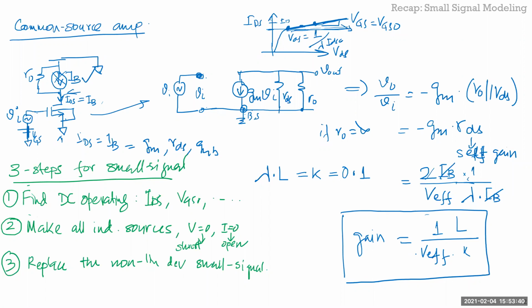So for higher speed, you'll see you need higher V effective. Okay, so you need a big excess bias because you need more current. So this is kind of showing you current per gate capacitance, because you can just keep increasing W as much as you want, right, to get the current.